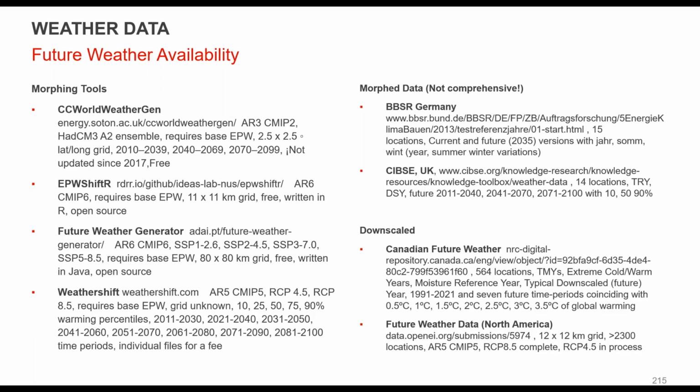For that temperature, go back through the data and find the average, the mean wet bulb that correlates to that. Similarly, there is a percentile for wet bulbs. If wet bulb's important for your design, and for some portions like cooling tower design it may be more important, you would have a wet bulb percentile and a mean coincident dry bulb to go along with that.